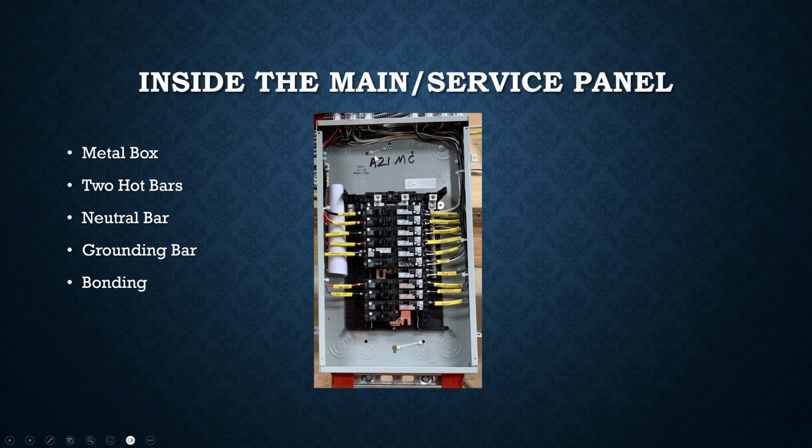You would essentially see three big black, like number 6 gauge or number 4 gauge wires from the power source that come in the box and plug into these big lugs right here. So here's one lug, here's two lug, here's three lug. All right, and there's going to be another one somewhere that's grounding the box, and that ground cable is going to run down into like a piece of rebar that's connected to the foundation if it's a concrete foundation or something like that. There's going to be a grounding rod somewhere. It's going to connect to that and come into here and ground to the panel.